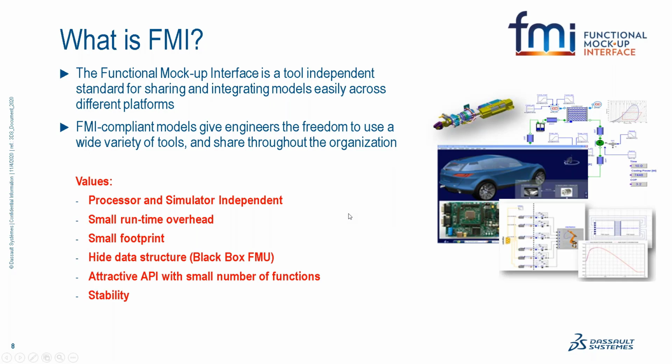So as I told you, the Functional Mockup Interface, or FMI, is a standard that has been used by many vendors. It is an independent standard, doesn't belong to any company, and makes sharing and integrating models quite easy across different platforms. The reason is that this standard is processor and simulator independent, and in general it is an XML file that provides inputs and outputs, and a binary or C code that is embedded inside this file. When you provide it to another tool, that FMU can be used by the other tool.